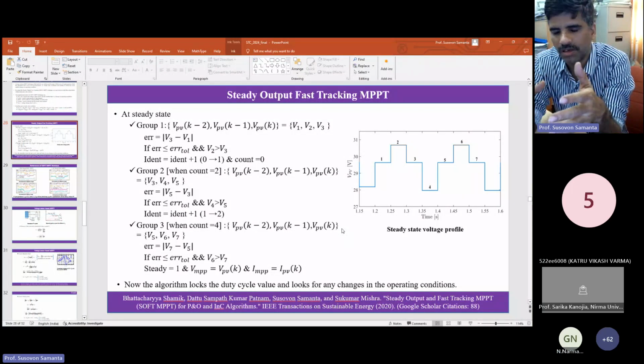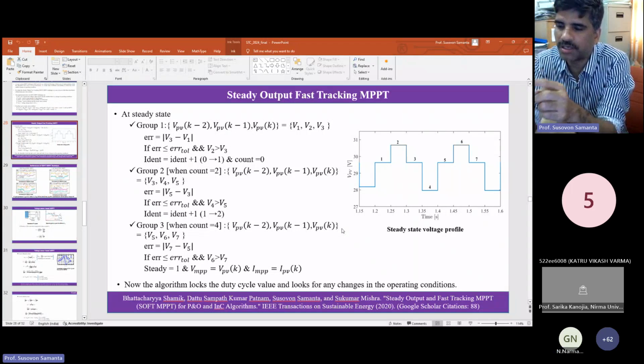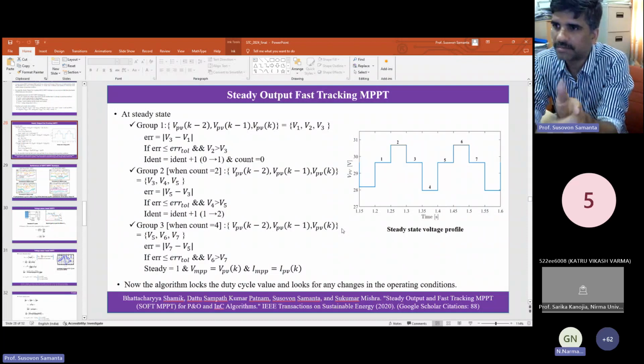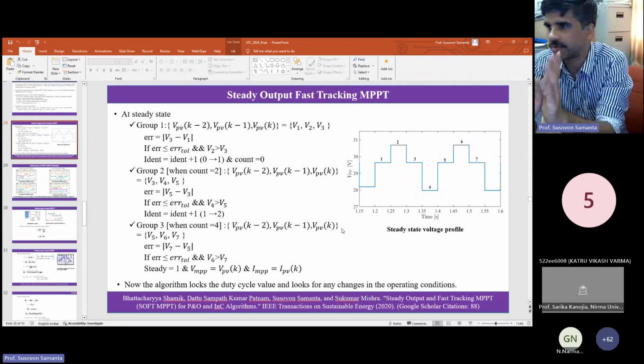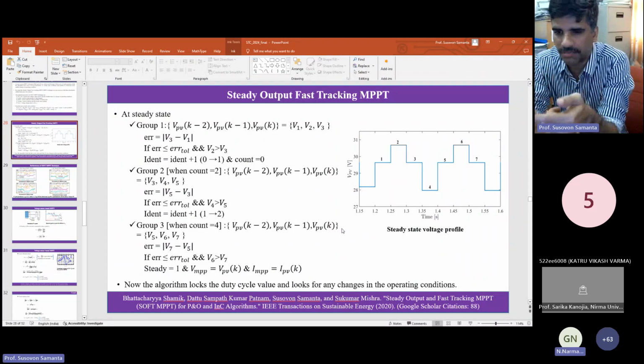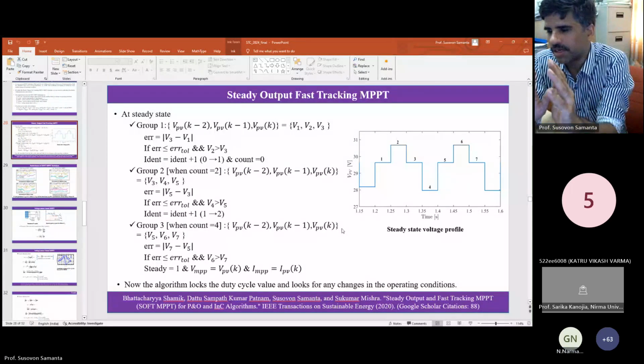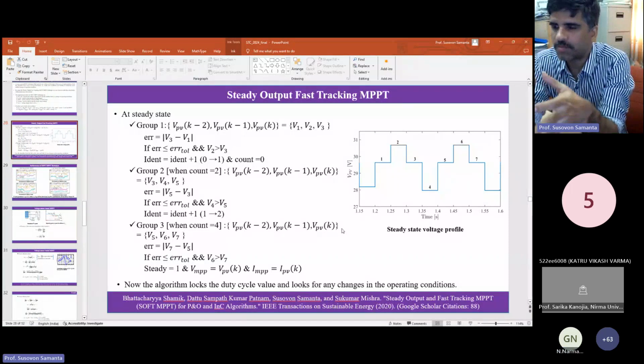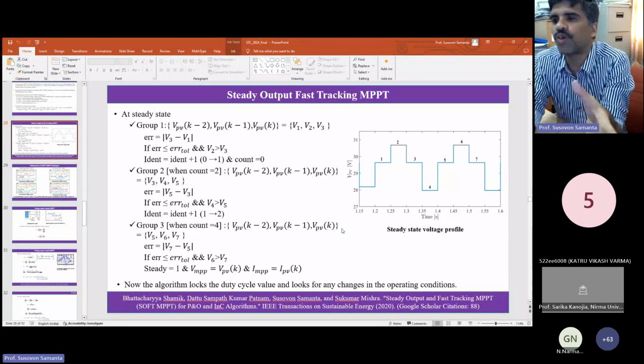For VREF control, you need to design the PI controller. For the PI controller, you need to find the dP by dt transfer function. That means when there is a change in the duty ratio, there is a panel voltage change, so you should give proper time for the panel voltage to settle. Another important factor: is there any need of changing the duty ratio too fast?